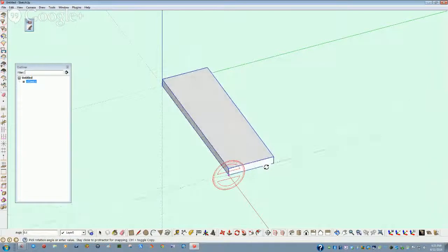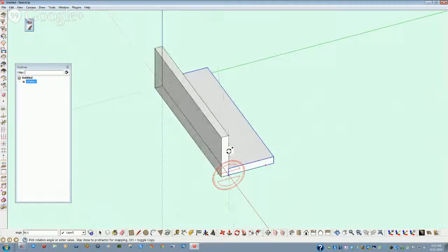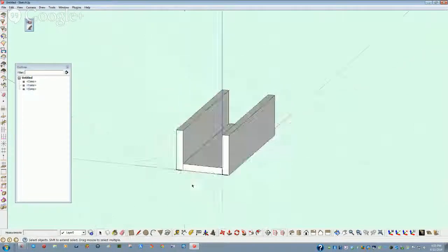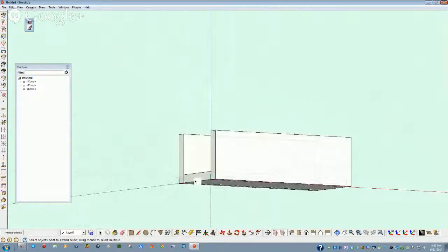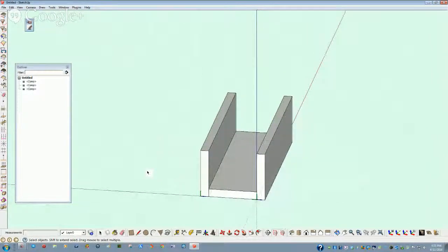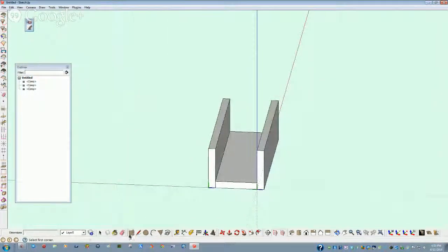So I'll show you what happens if you don't hold just spacebar or control key down. See, it just kind of goes, you can move individual components. So I'll do this again. Get away from it so I can close it. This is going to be a simple butt jointed box. Now you can see I already have two sides. Another way that you can create surfaces, and I'll say surfaces rather than elements, is you can do it with this tool, called the rectangle tool.